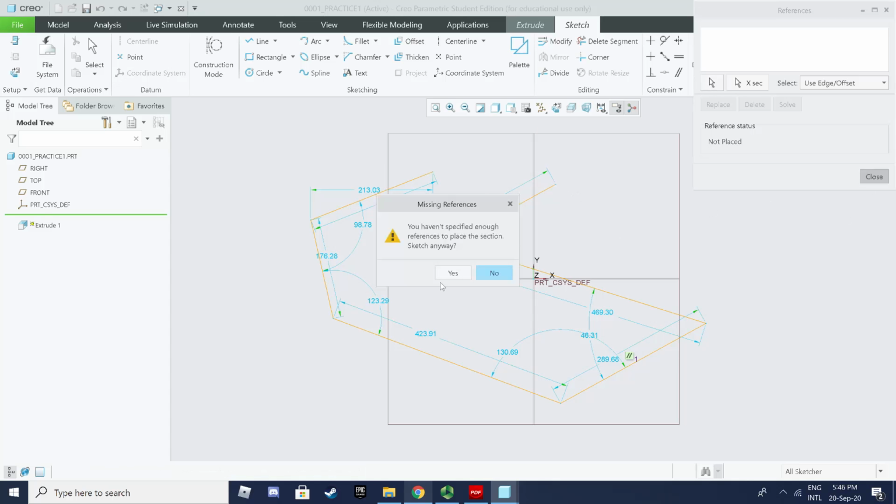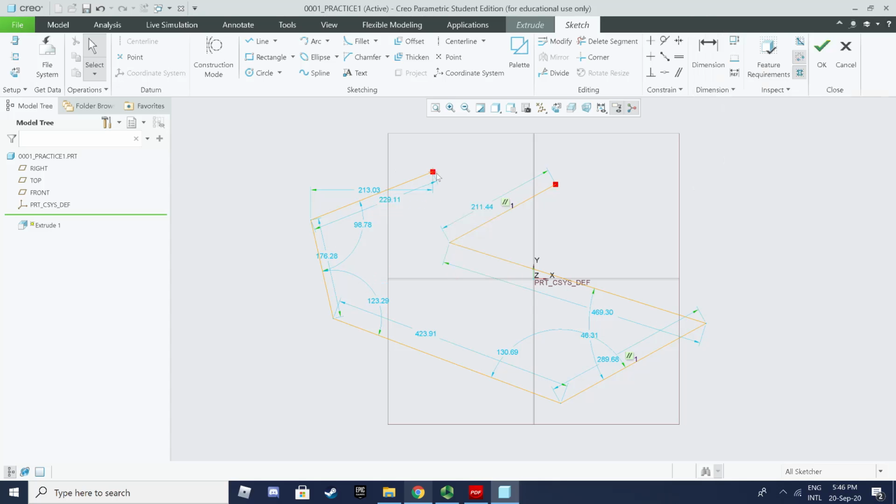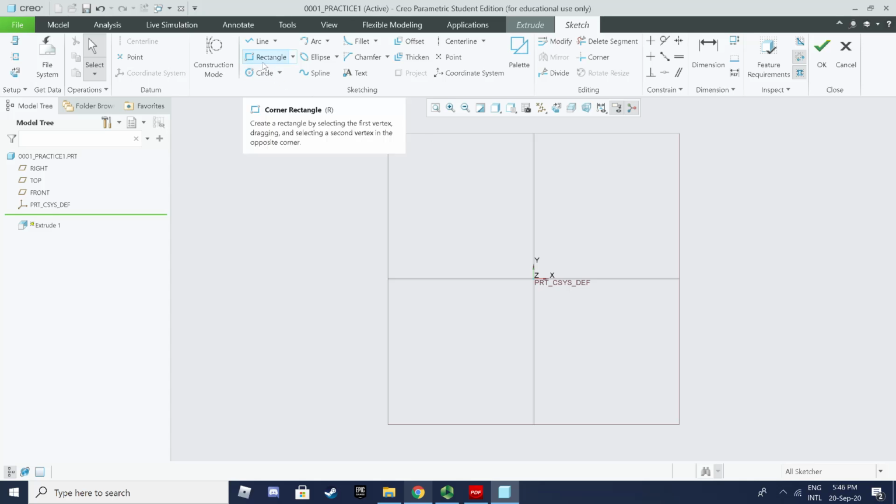So for a 3D model, if you don't establish any complete area, then it cannot proceed with the third dimension, where you need to give some thickness. Okay, so make sure that you complete the shape. If you want to delete everything, just drag everything here, then go to your keyboard and press delete. Okay, all right, so let's do something very simple first.